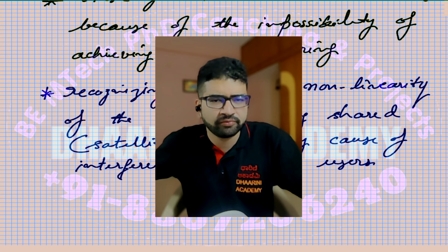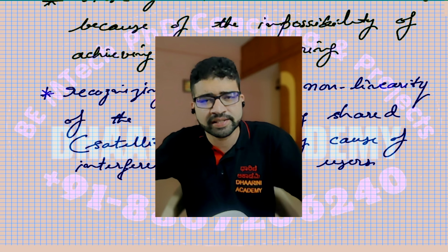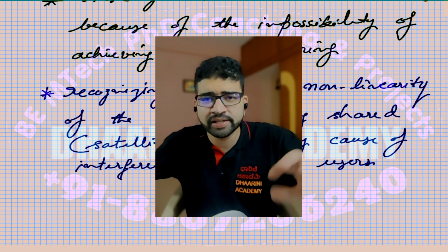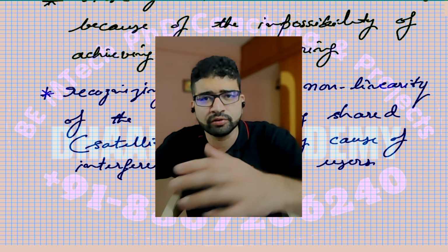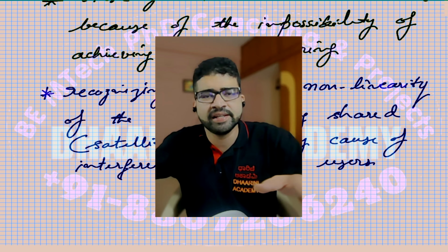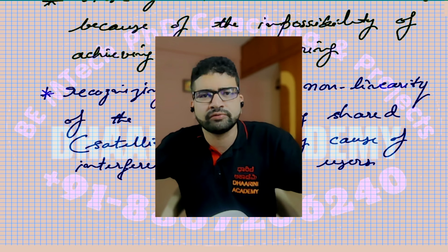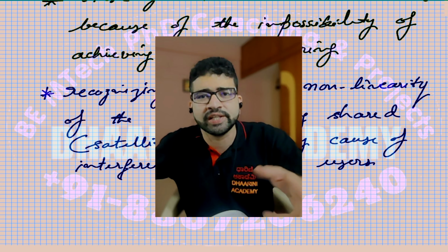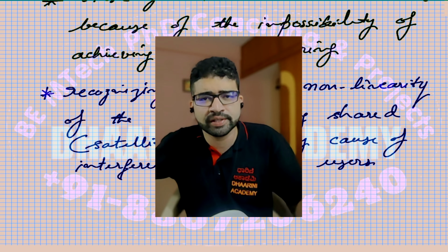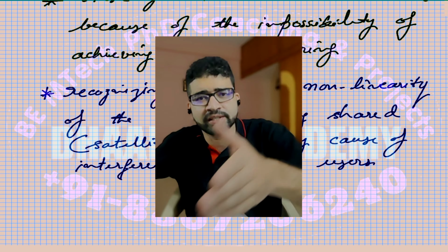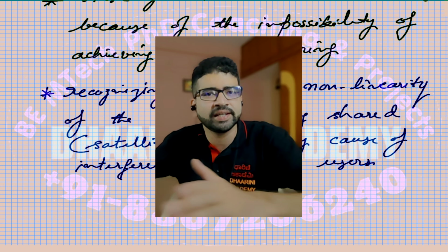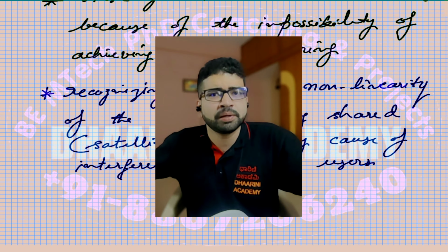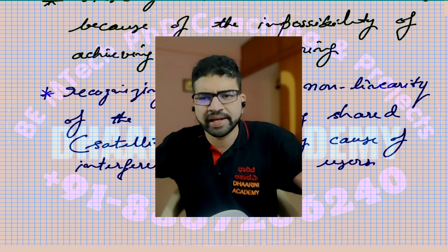If I have a cos omega t as input, it generates cos omega t, cos square omega t, cos cube omega t, and cos to the 4, which in terms are the integer multiples or harmonics of your cos omega t, correct? Because cos square theta is 1 plus cos 2 theta. So if I have cos theta over there, cos 2 theta comes at the output, cos 3 theta, 4 theta, etc. will definitely come in the output. It's actually causing the problem, right? So that's the problem. I identified that now.